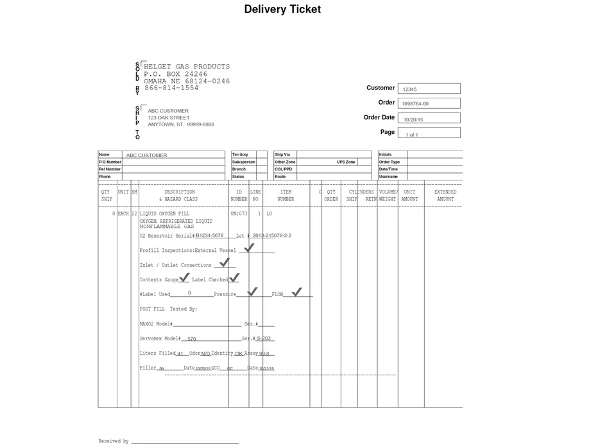We document the liters filled. In this particular case, there were 41. We do an odor test, and we had none detected. Because we tested with the Servomex 570, so long as we are above 99% assay, then the identity is okay, because the Servomex is an oxygen-specific analytical piece of equipment. You'll document your initials and the date you did the fill. You'll turn your ticket in, and either that night or the next day, the QCU member will release the ticket.